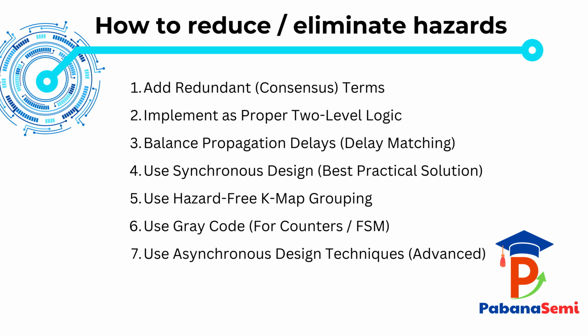Sixth, use gray code in counters and FSMs. Gray code ensures only one bit changes at a time, reducing multi-bit transition hazards. Finally, for advanced systems, apply asynchronous design techniques carefully, using formal hazard-free logic methods.